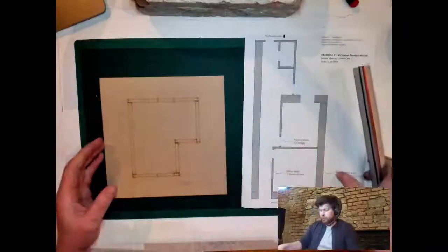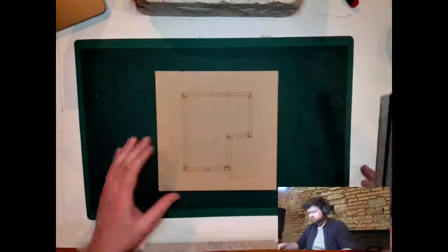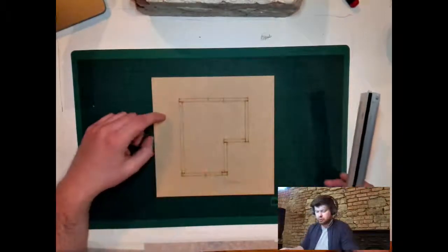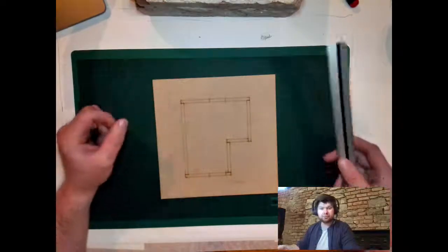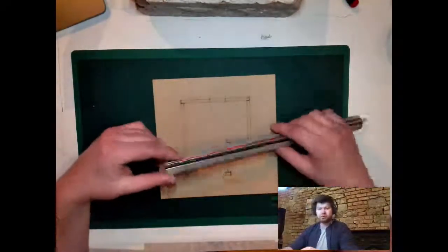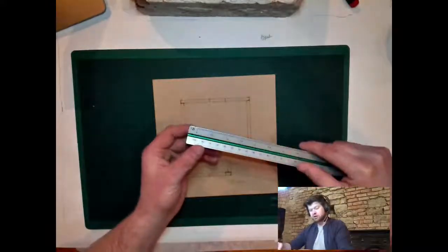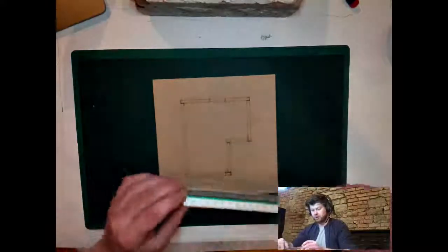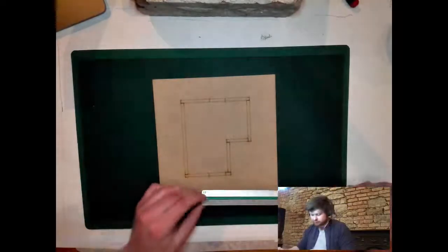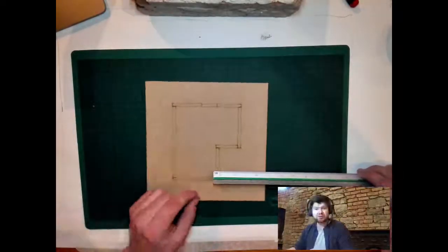We'll start off with reading or measuring some things with the scale ruler. So this plan, which is part of exercise A, is at 1:25. So I'm going to pick the scale on my ruler at 1:25. And I can use this scale now to measure things on this model. So for example, if I measure the thickness of the wall,